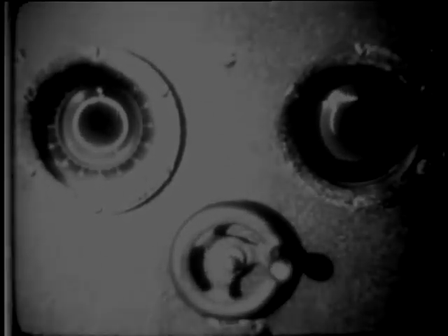To measure range even more accurately, crank this hairline around until it's on the target pip. That makes the echo appear as an expanded pip on the fine range scope, there at the right. It's also a J-scope and shows you an enlarged 2,000-yard segment of the set's entire range. With these 2 scopes, you can locate a target to within a few yards.